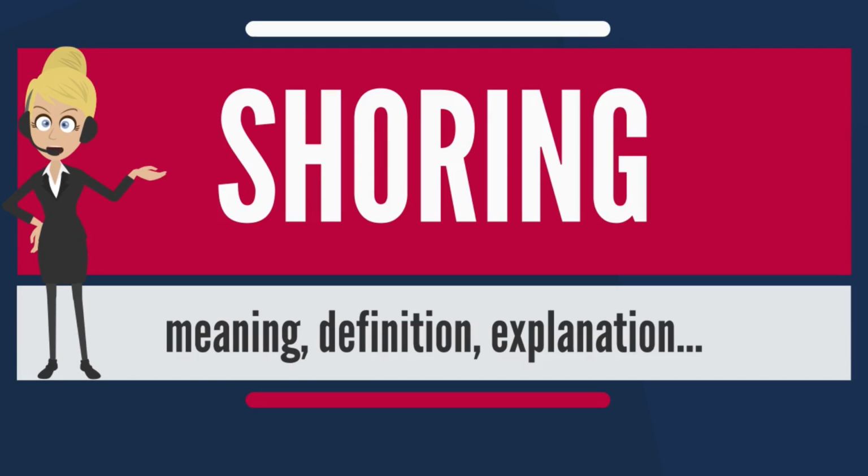Shoring is commonly used when installing the foundation of a building. A shoring system such as piles and lagging or shotcrete will support the surrounding loads until the underground levels of the building are constructed. During excavation, shoring systems provide safety for workers in a trench and speed up excavation. In this case, shoring should not be confused with shielding. Shoring is designed to prevent collapse, where shielding is only designed to protect workers when collapses occur.